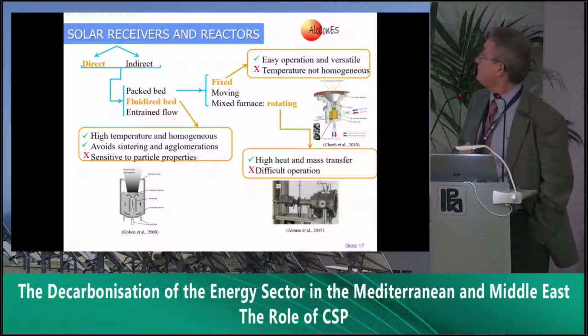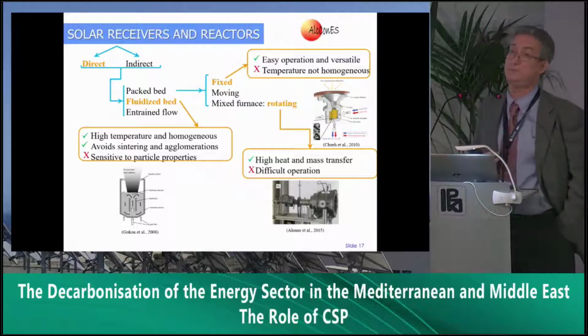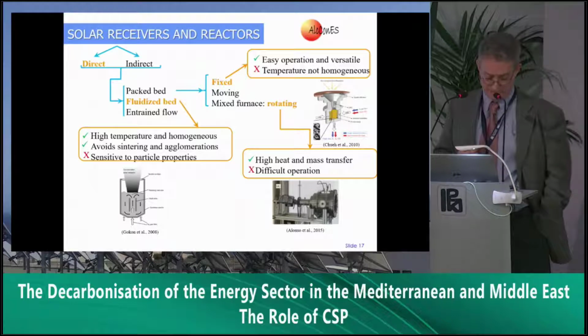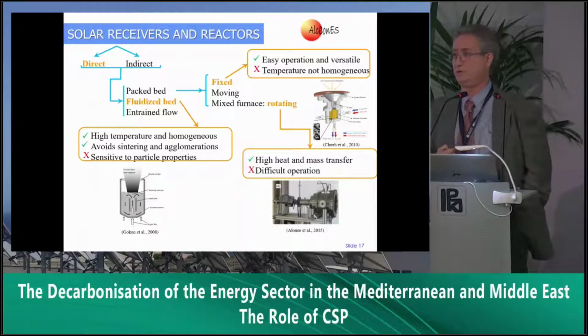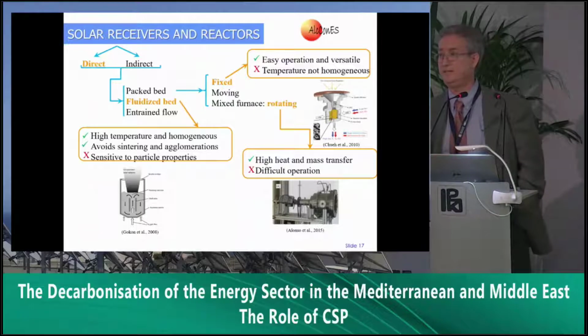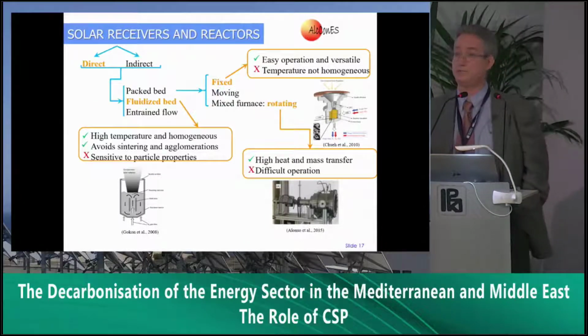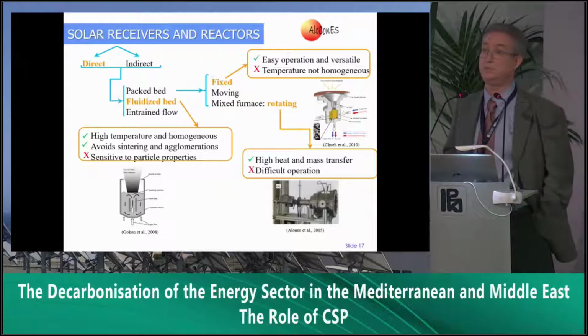In the case of other solutions like rotating reactors, you can improve and be more versatile, for example controlling the residence time, etc. But most of them are very tricky to operate. Material sticks to the walls. You have a lot of problems because you have to rotate the system, but at the same time you have to have an airtight system. So that's not simple when you are working at more than 1000 degrees C.